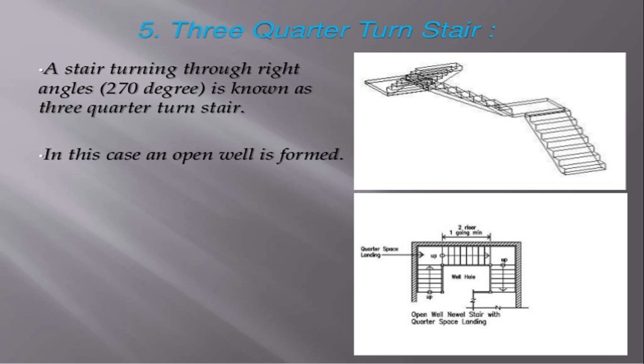Here three-quarter turn stair means the topic itself explains that they are having three turns, three-quarter turns. So this one is one quarter turn, and another quarter turn. So one, two, three flights are provided in a single design of a stair. As you can see in this plan itself, three turns are provided. So this is termed as three-quarter turn staircases. In this case, an open well is formed. You can see in the plan itself, there can be an open well, so that from the stair you can see the bottom floor. Okay.